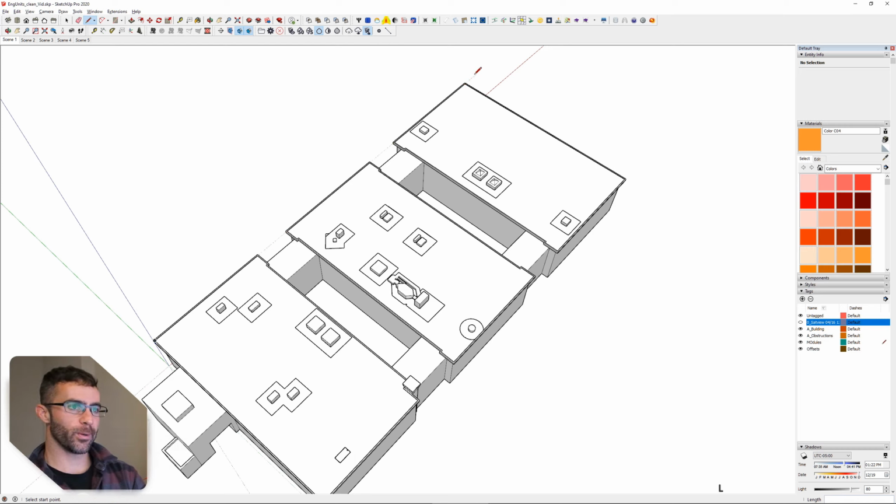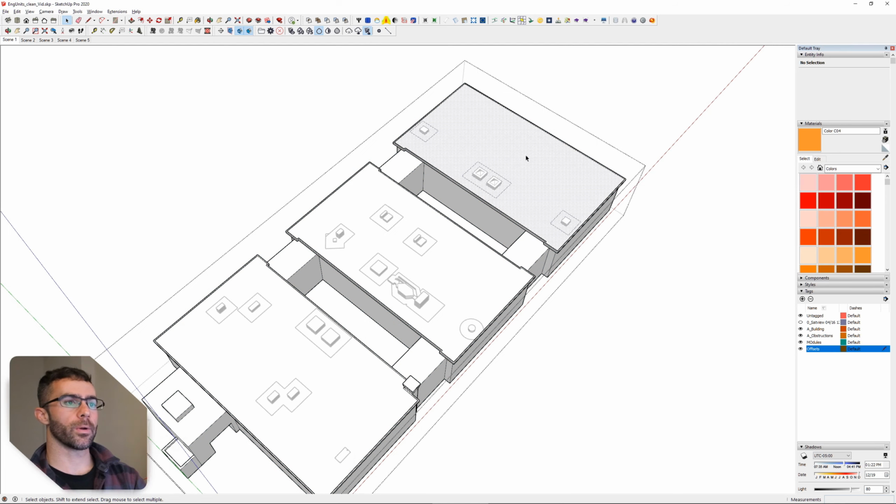But if we were to include this, depending on your fire code, fire official, that's 258, and that is 267. So that exceeds it. So they may or may not be comfortable with that. However, this axis is only 114 feet. 114 is clearly less than 250. So we're going to say we're good with 4 foot offsets. So now we go in here, offset command, 4 feet.